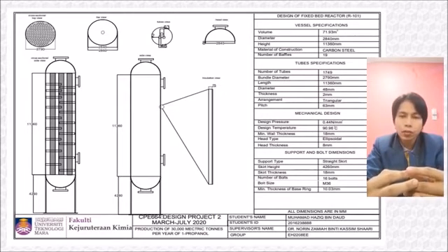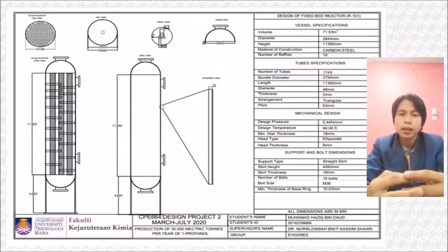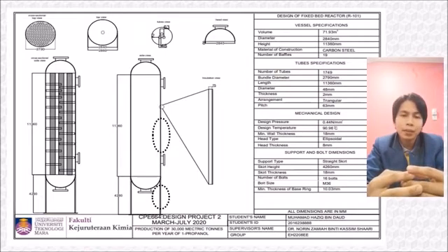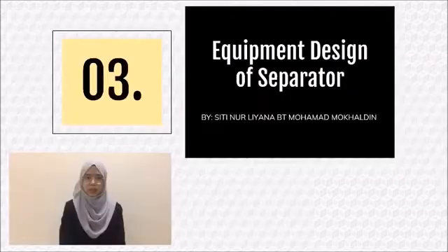The reactor also consists of an insulator, which is mineral wool, to absorb excessive heat and to prevent the reactor from overheating. The wall thickness and the skirt thickness were calculated to be 8 mm and 18 mm respectively, which is sufficient to withstand the dead weight loads and bending moment imposed by the vessel.